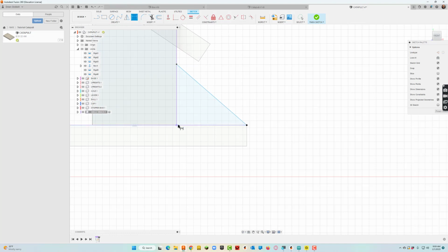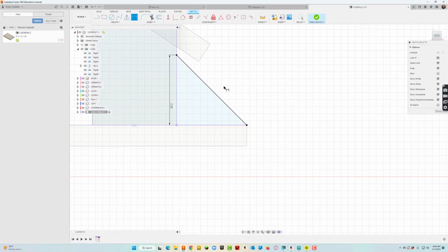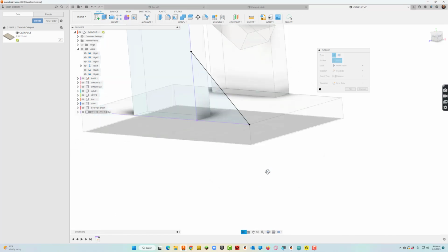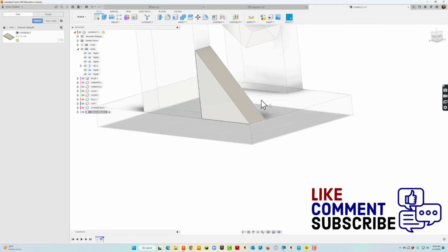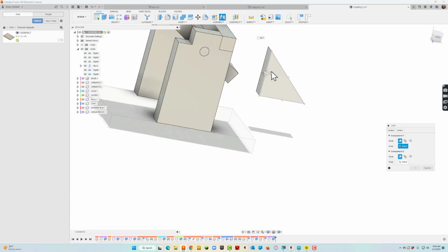So this number here, from here to here, that's a 2.5. That's doable. So from this point to this point, if I look at that, that's 2.17. Good night. I'm just going to put 2.5 to make those sides even. So I'll extrude that now. Pick this side, and I'll just make it go back negative 0.75. Now I could come back here to the whole thing. So that, in a nutshell, is how you create the catapult.